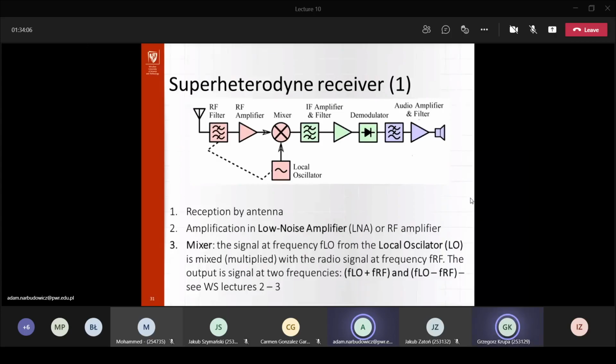Yeah, I guess that's possible. And also, the next conversion can give us better filtering of the intermediate frequency, but it will also introduce noise. So can the previous stages intermodulate with the next stages of intermediate frequency? So basically you are referring to the case when you have two intermediate frequencies, and the first is going lower and the second is also going lower. Yes, so in theory, yes.